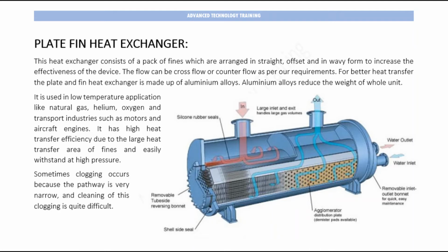It is used in low-temperature applications like natural gas, helium, oxygen, and transport industries such as motors and aircraft engines. It has high heat transfer efficiency due to the large heat transfer area of fins and easily withstands high pressure. Sometimes clogging occurs because the pathway is very narrow, and cleaning of this clogging is quite difficult.